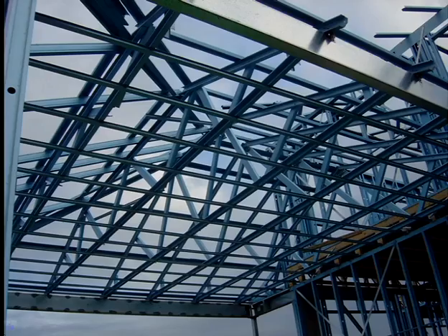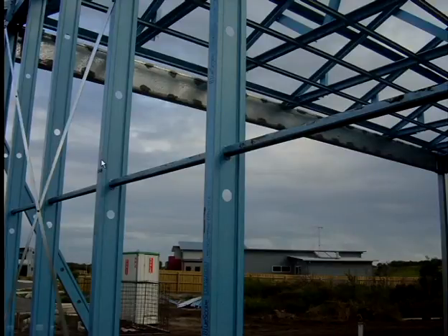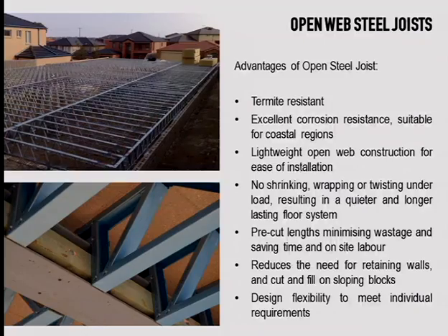And so these are trusses. You see another lintel there, just showing you the elements, how they are, just showing you the similarities. This is the correspondent of noggins, just to reduce the height of the studs so that they don't tend to buckle anymore. And there are a couple of systems which are more interesting that generally you won't do